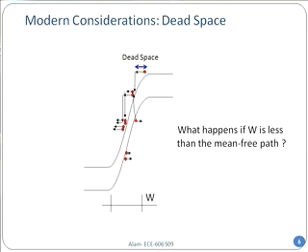As a result, when the electron comes in from one side, it may be able to go from one side to the other side without ever scattering. That's ballistic transport. If you don't scatter, of course, you cannot really do any impact ionization, right? You need to scatter with other electrons. So in case of ballistic transport in a highly doped junction, everything that I told you might not be correct. In this case, there is what's called a dead space, the space you need before an electron can impact ionize. The first one has to start. Now, if it is a huge junction, you can impact ionize many times. You can start with 1, get out with 10,000.